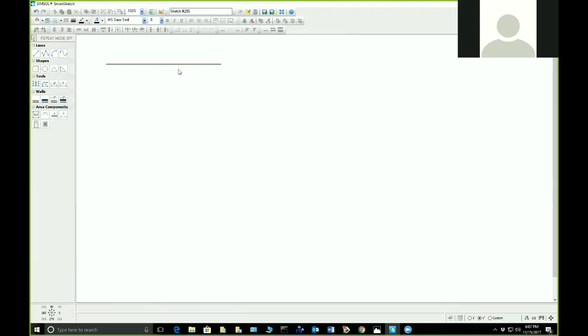Now this is an object. As I select it, that highlights it, and my edit bar should come up down here and be displayed. So if I need 37 feet, I hit the tab key and select 37 feet 5 inches instead of 6.